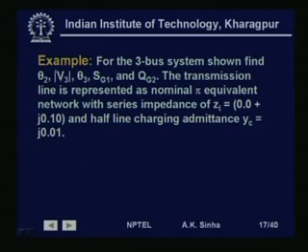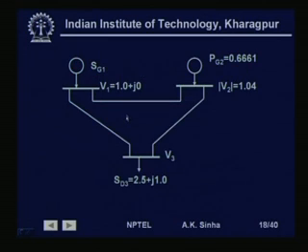So, this is the system that we have, and now we will see how we set up the equations and solve using Newton-Raphson power flow to get the values for the unknowns, that is theta 2 for this, V 3 and theta 3 for this, and of course, after we have got those values we can compute P g 1, Q g 1 and Q g 2.